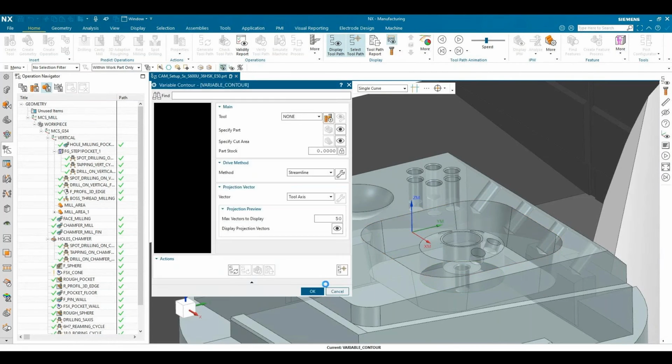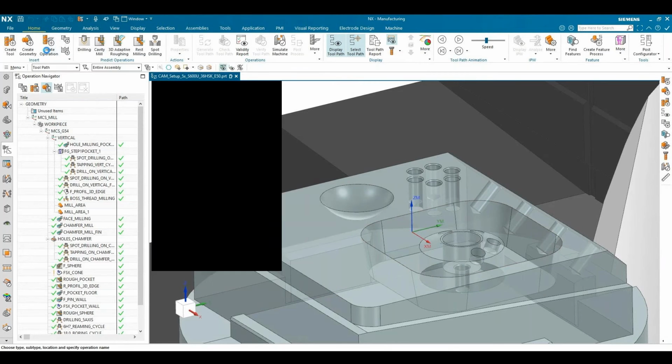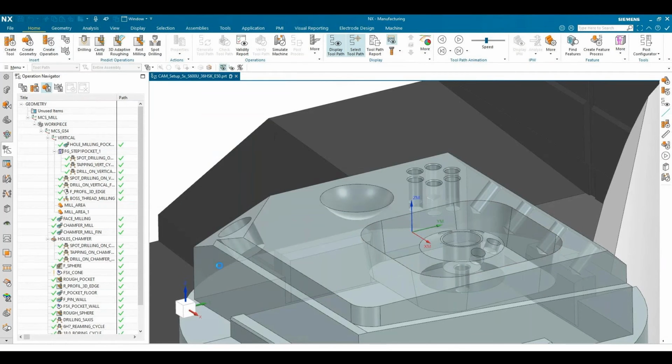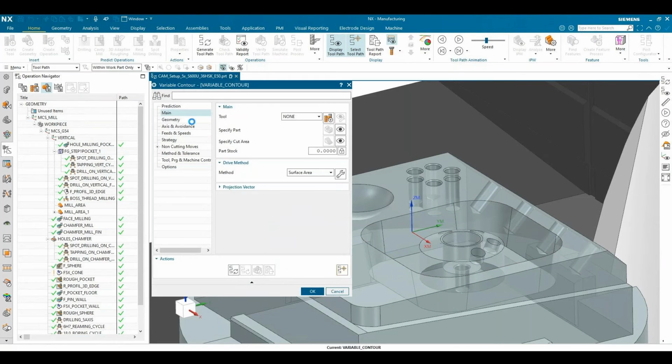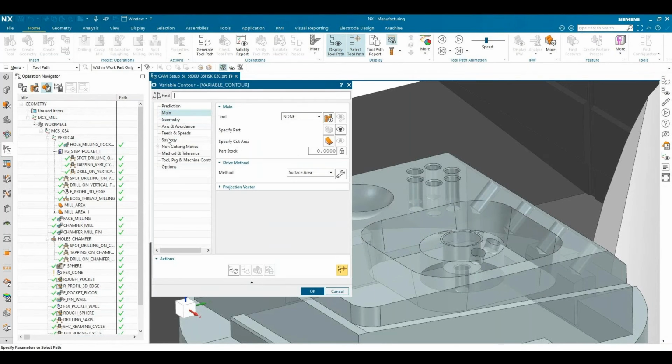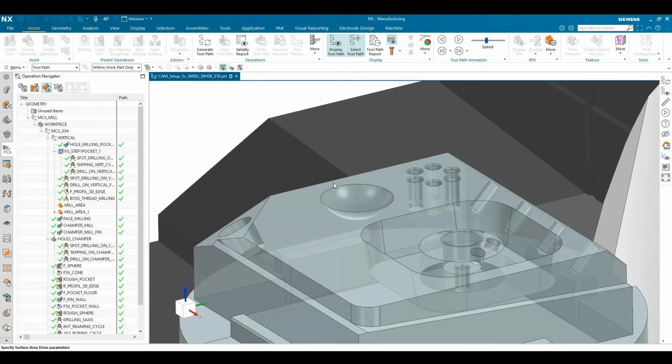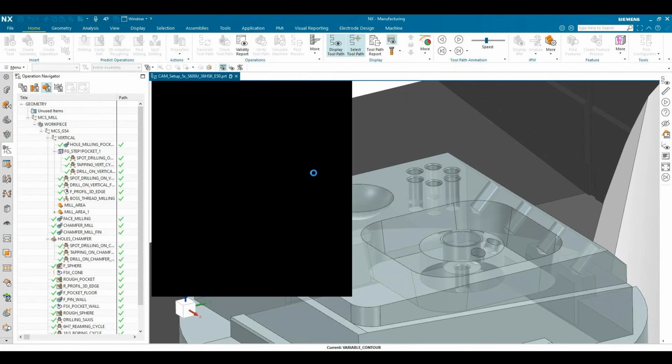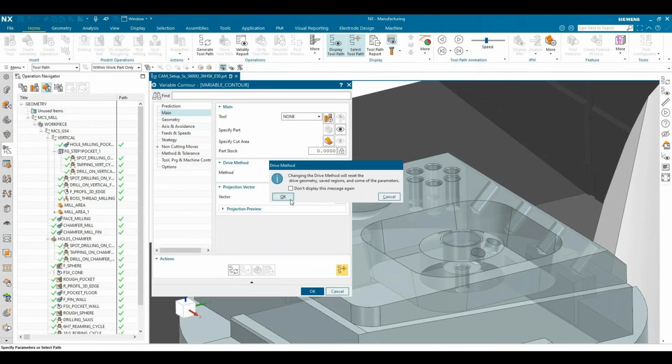So now if I do it the manual methodology, where I would just go and create the operation without any type of geometry in there, the dialogue is meant to go top down, left to right. So if I process like I'm supposed to, on the main node top down, the first thing I need to do is go in here to my parameters. There's nothing in there. There's nothing for it to pick up.